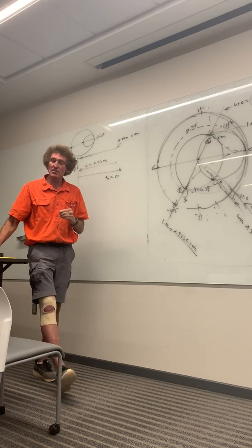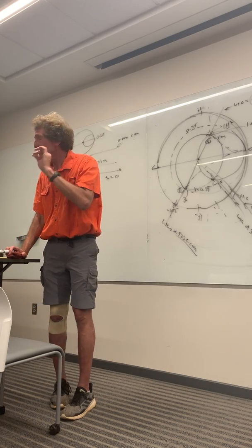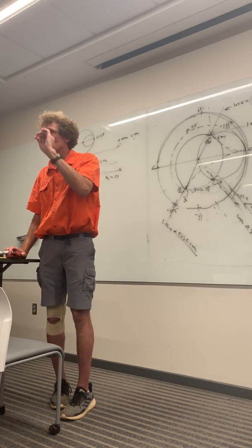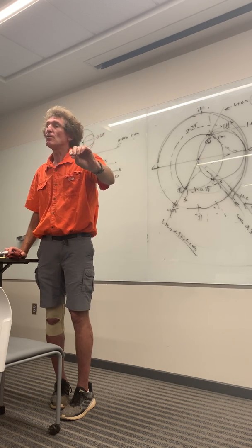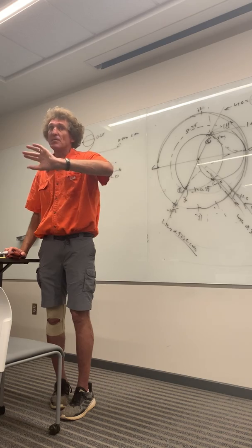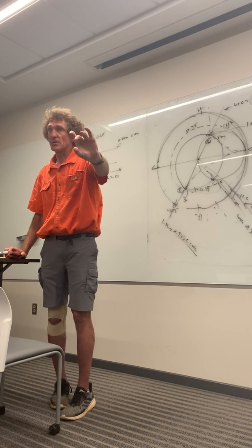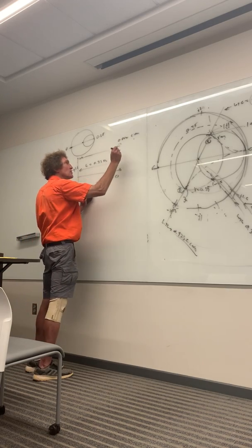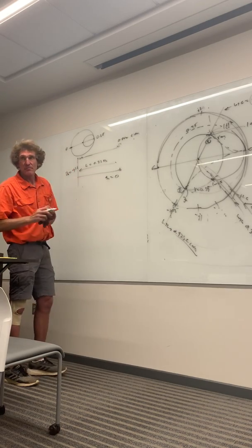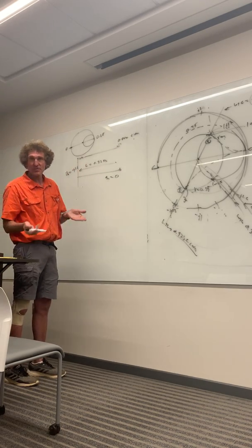And in my EMC course, I get into it. Crosstalk is literally the voltages on one part of a circuit influencing voltages in another part. They're being felt on other parts of the circuit. And that's what you don't want. And that's why I never tell people to put an open circuit, always a short. But just for completeness, we're gonna do the open circuit deal.